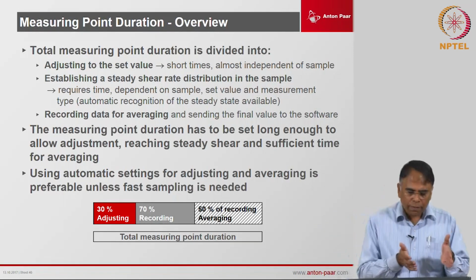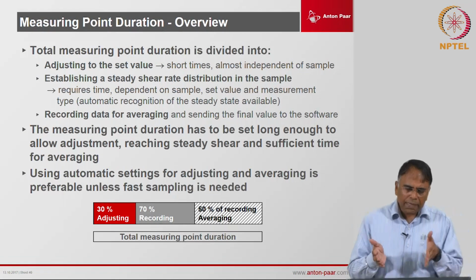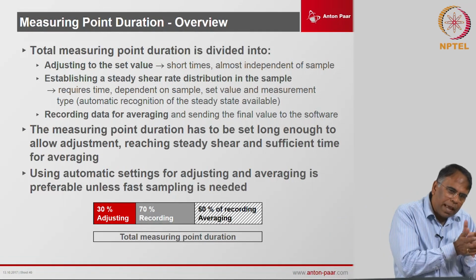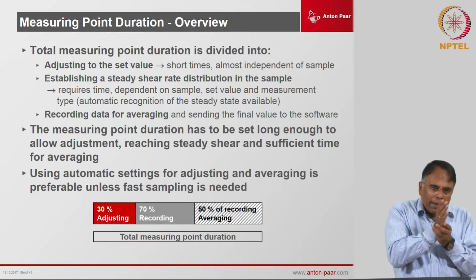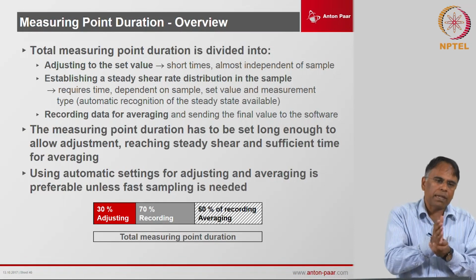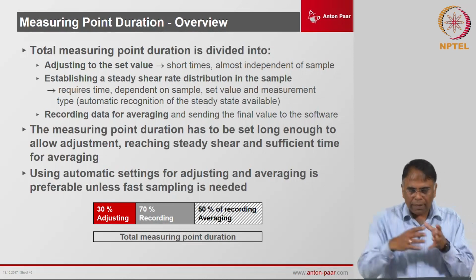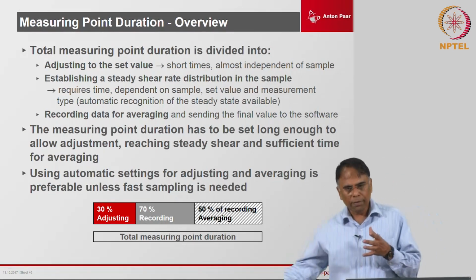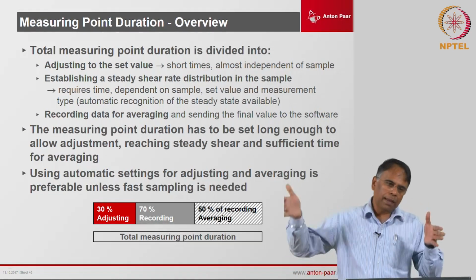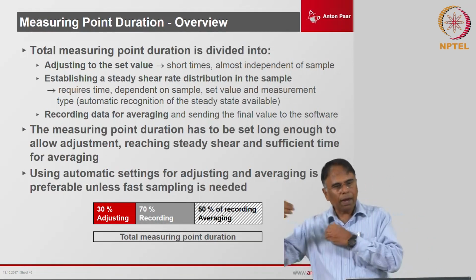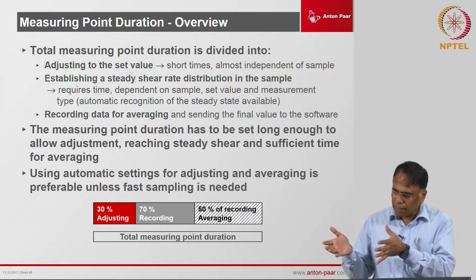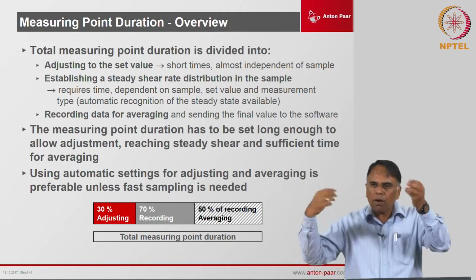If you look at a measuring point duration, the first 30% of the time is utilized to apply the strain or stress that you have defined. Then the next 70% is used to record the torque over the complete event, and after that 50% of that time is used for averaging out the data, because you get a lot of information.